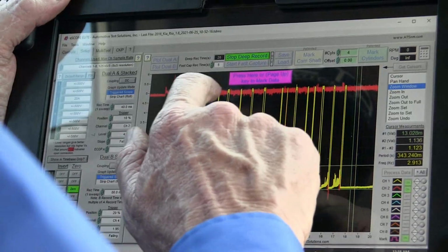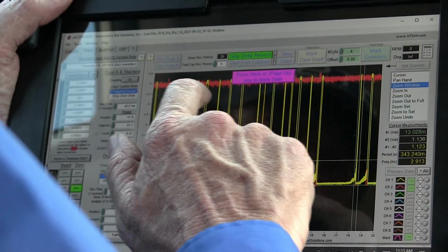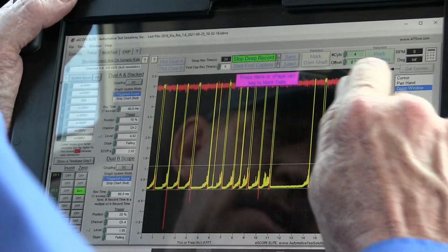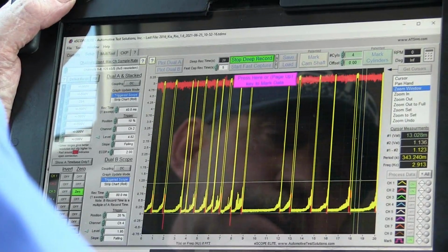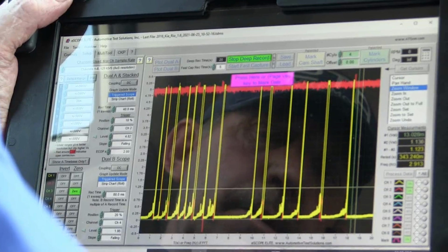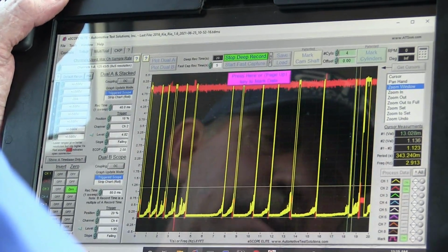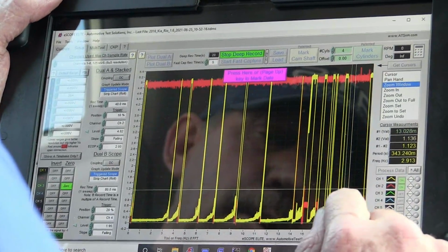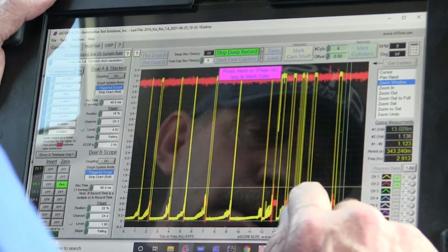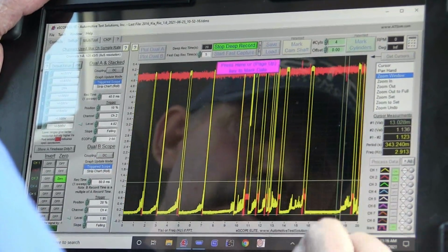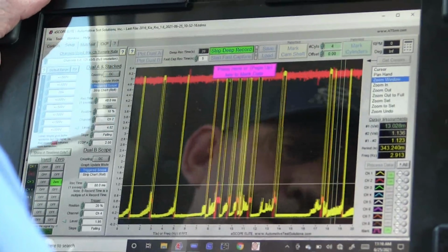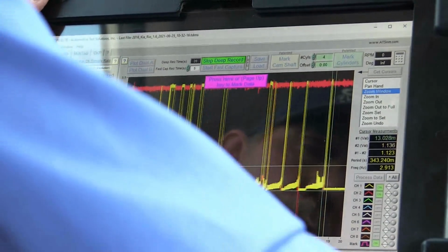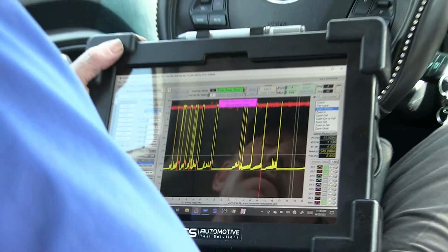That's really interesting. It's like the ground or something is opening on that circuit, because that ground going open would get me 5 volts. So maybe we have some kind of a connection problem. And we've got something going on in between where we're grounding here too, because that should just be a smooth, good line. Let's rev it. So let's drive it and see what we got.